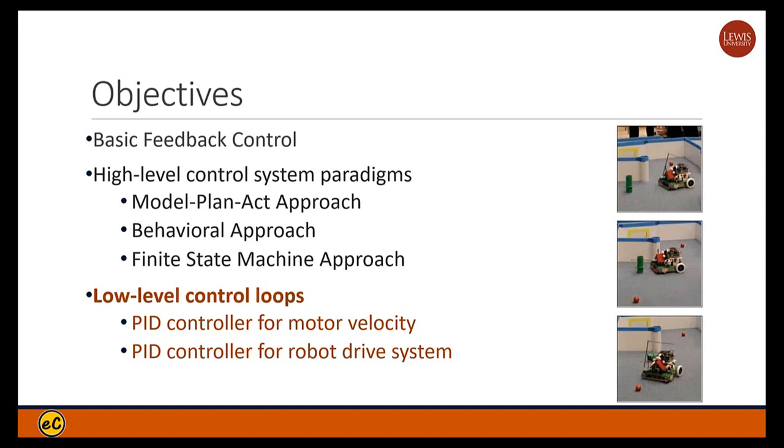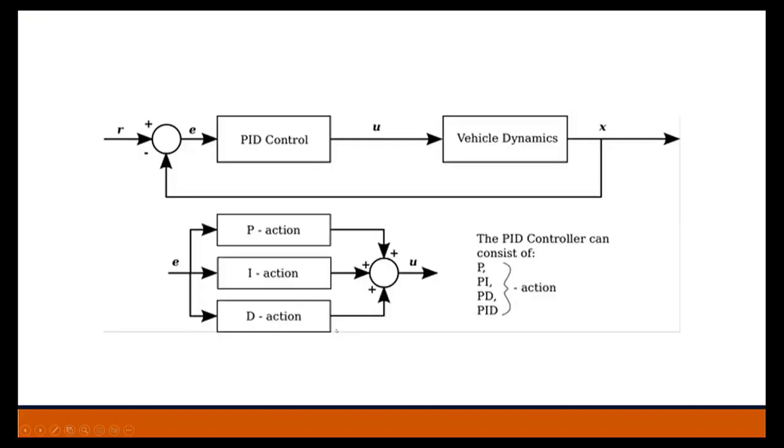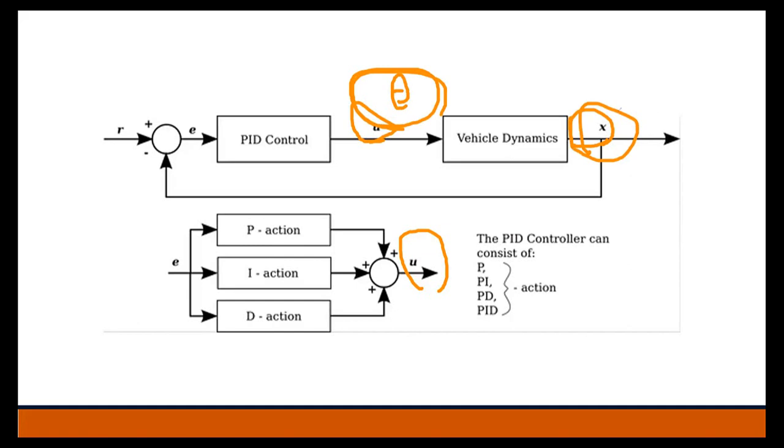We are talking about these different control loops, but today we are looking at the low-level loop, the PID loop, which is why I highlighted it. So let's look at this loop. You have some system variable U that you want to control. This is your control variable, say theta or something. It creates a displacement. So this one is the control variable, and this one is the physical displacement, or the observed location.